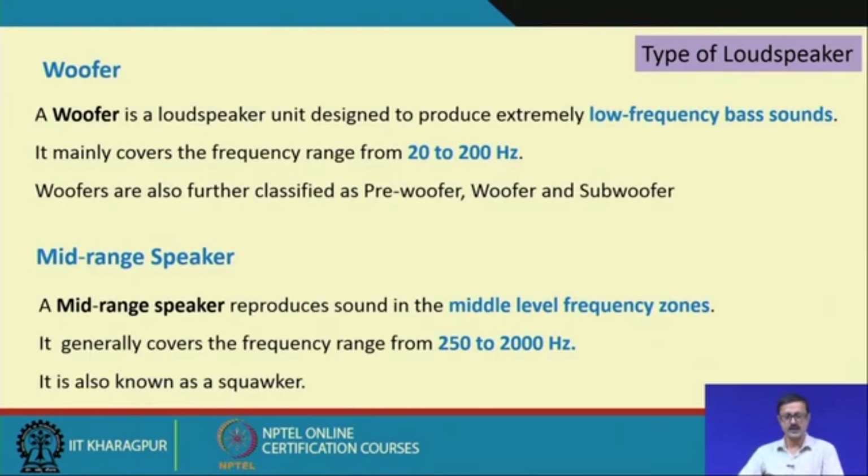The woofer is a kind of loudspeaker which delivers the low frequency and bass sound, approximately 20 to 200 hertz, and they are further classified as the pre-woofer or the subwoofer. And the mid-range speakers, as the name suggests, take care of the mid frequency level, around 250 to 2000 hertz, and deliver those mid frequencies properly. But this may not be very effective for low or high frequency. It is also called a squawker.